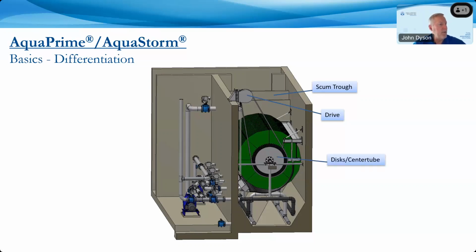You can see the end of the center tube there, but then you can also see these hoppers. Due to the configuration of these basins, and just to give you a sense of scale, those hoppers are approximately 1 meter deep, about 3.3 feet deep. And so we're actually settling solids and having some concentrating occurring within the process. And of course, your pump and valve gallery.